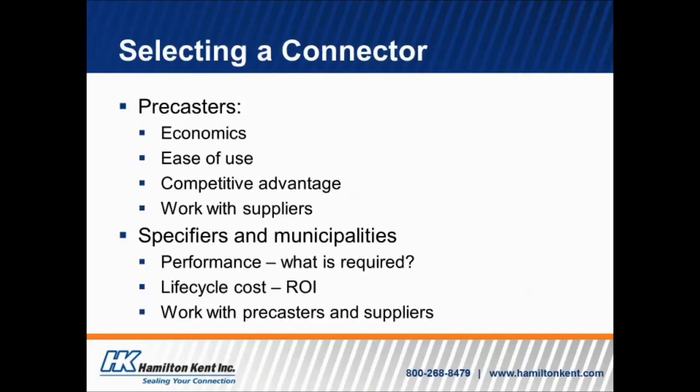So selecting a connector, and basically we're looking at this from two different perspectives. One would be the precasters, and that's going to come down to a few things. One is economics. What makes most sense financially for the plant? If you're going to use a casting connector, there's going to be investment in mandrels, but you're also going to save on some of the labor to install a mechanically installed boot.